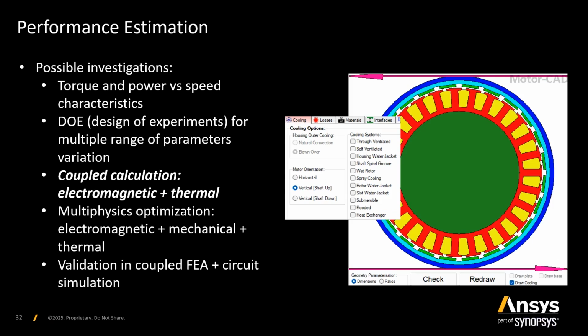Here we see that there is no specific cooling. It's only air blowing over, remember that this vehicle will be up in the air. So there is no forced liquid or other specific options. A reminder as well, we don't have any impregnation in this material. The slot liner is actually part of the coating of the stator lamination.